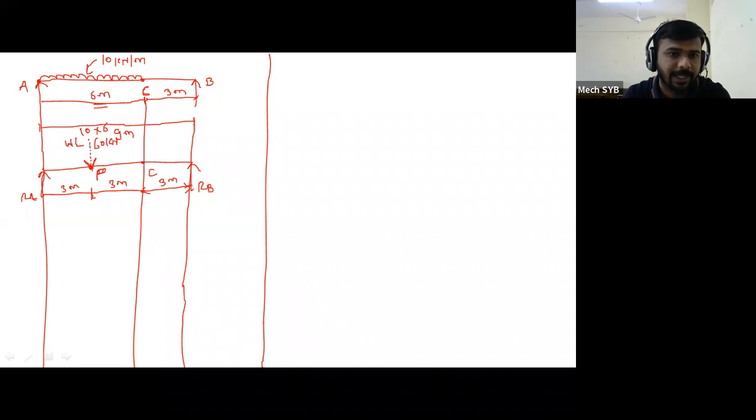But we are not doing any shear force calculation at point P. We have to do SF calculation and BM calculation only at the original points in the figure, A, B, and C. Don't do any calculation at point P. We have named it point P only for our understanding. Okay, so now this is the second loading diagram, where we have converted the UDL into a point load.